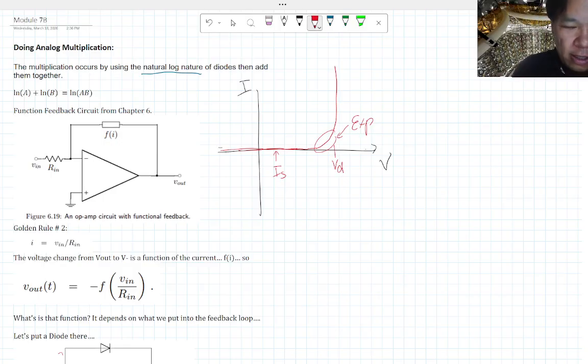Okay. But when we start talking about op amps, instead of an inverting amplifier where you put a resistor here, this could be anything you want. It can be a capacitor, which makes it a low pass filter, or it can be a diode.